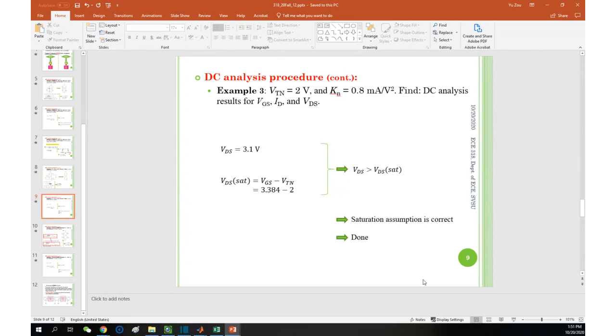But if equal, it's actually not a stable amplifier, so we are definitely going to try to avoid that. Therefore, we consider that as non-saturation. We don't want to use that kind of MOSFET circuit for the amplifier circuit. It's not stable. Any other questions? Anything?